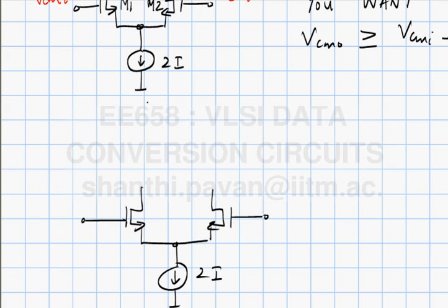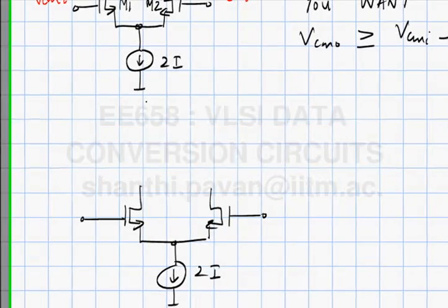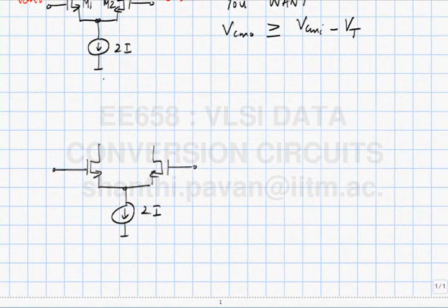So, if I want a dependent current source, I want to change the top current source to make it equal to the bottom current source. So first of all, I must have a current which is capable of being changed. What is the simplest device structure you know which will allow you to push current and control the current using a knob? What kind of transistor? A PMOS transistor.